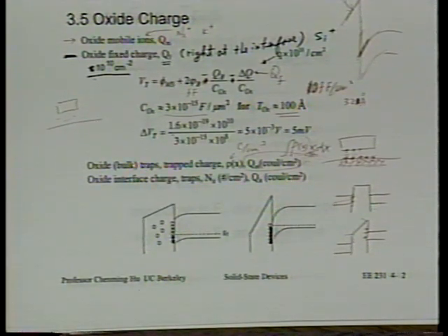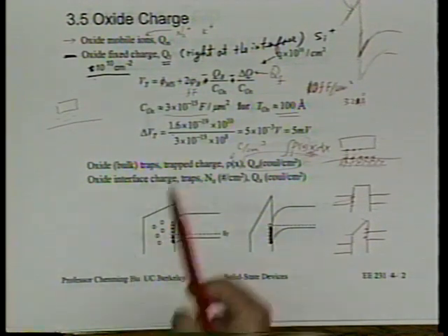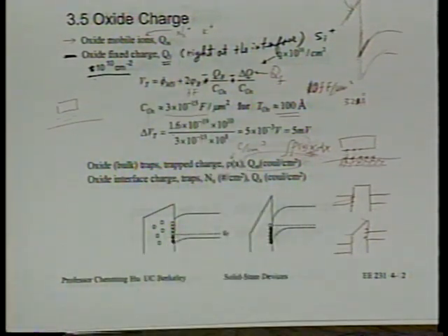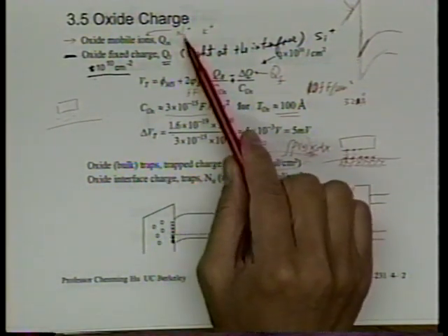are present everywhere. If you use glassware in the fab, then your whole fab will be contaminated by sodium, because glass contains sodium. And for that reason, we never use, quote, glassware. We use quartzware in the IC fab. They are made of fused quartz, and they are free from sodium, as one way of avoiding sodium contamination. And all the chemicals and the gas also have to be particularly pure from sodium.